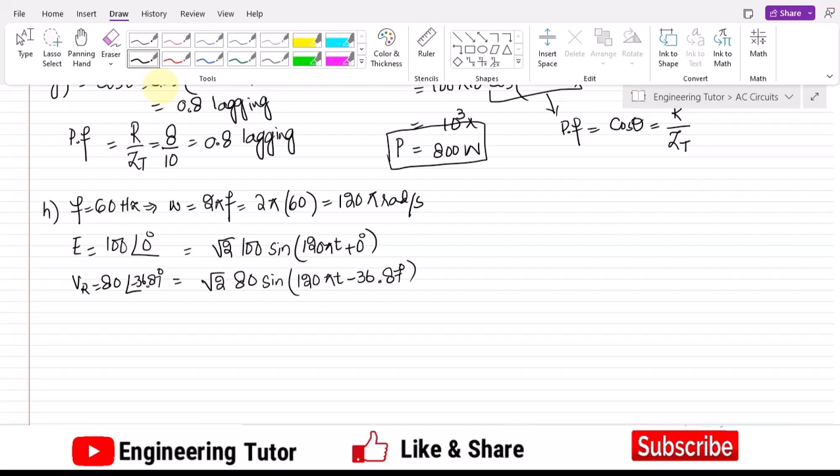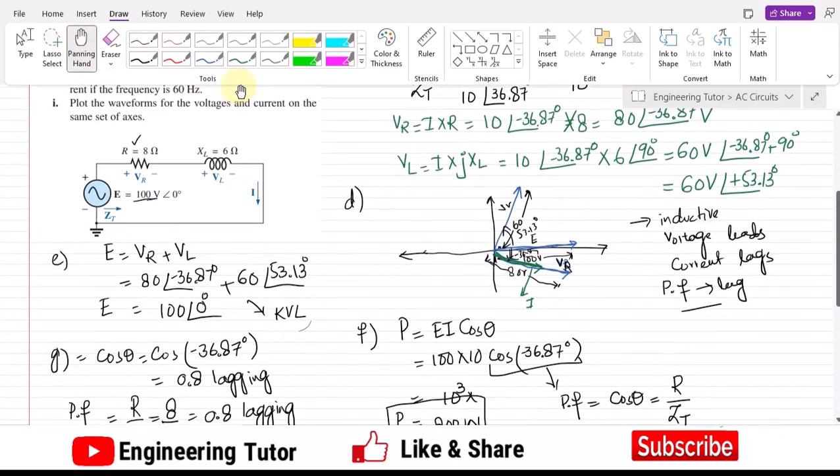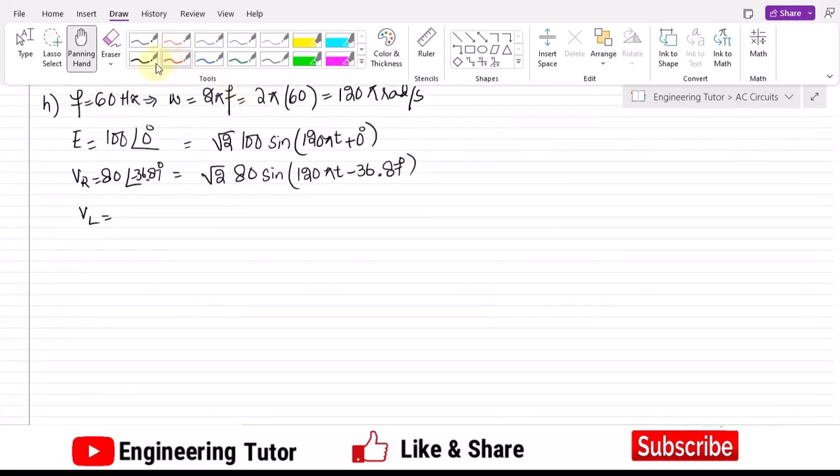minus 36.87 degrees. Similarly, the value of V of L was 60 volts and the angle with it was 53.13 degrees. So the same procedure here: square root of 2 times 60 and sine of 120 pi t, and the angle is 53.13 degrees. Okay, so this is about all the voltages.